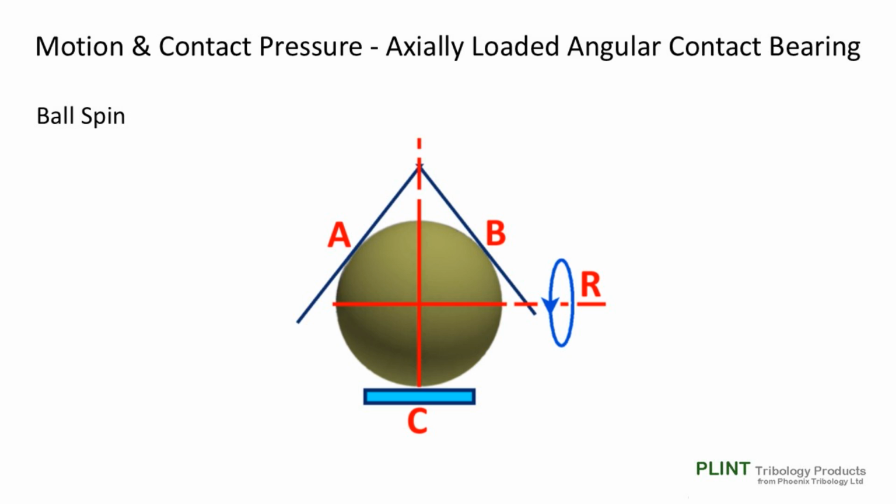If the ball is running around a circular track instead of in a straight line, there will be spin in all three contacts. Spin is defined as rotation within the Hertzian contact. This is what develops traction forces within a pure rolling contact. However, because the traction developed by the spin in all three contacts must be balanced somehow, there is bound also to be slip in each contact.